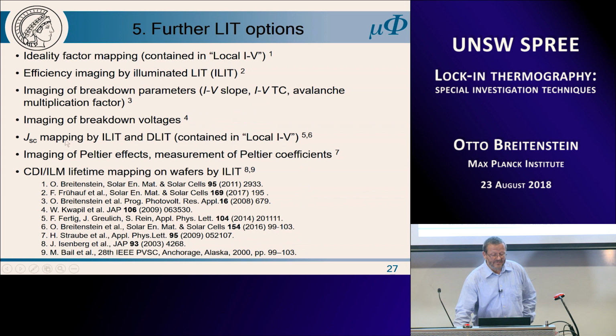I have shown JSC mapping here, and what I haven't shown is imaging of Peltier effects. This is also nicely possible. Even Peltier coefficients can be measured quantitatively. And also what I haven't mentioned here is carrier density imaging or infrared lifetime mapping, which is the same. Lifetime mapping on wafers can also be performed by illuminated lock-in thermography. You see the references to all this here.